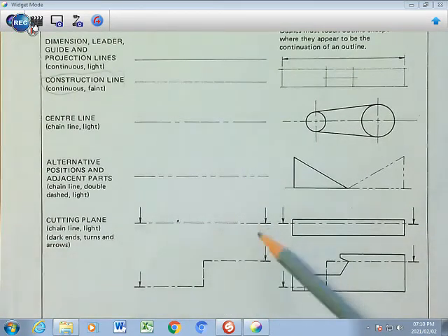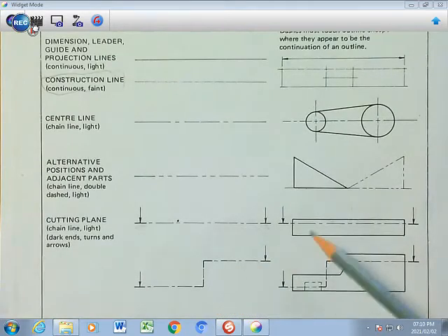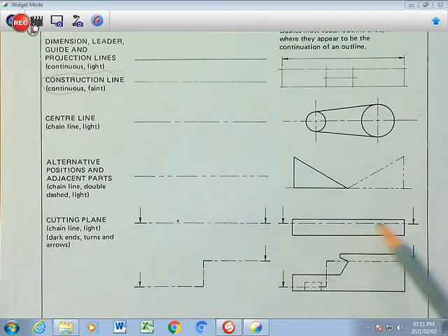The cutting line is normally shown where you are going to remove something. So if this is a piece of metal or piece of wood, and I need to cut through there to remove that top part, the arrows will be on the side which will be removed. Alright, so you can use a hacksaw or a grinder to cut through that section there. The section also comes in a staggered format where you cut like that, you know, staggering that cut as you can see here in the example.